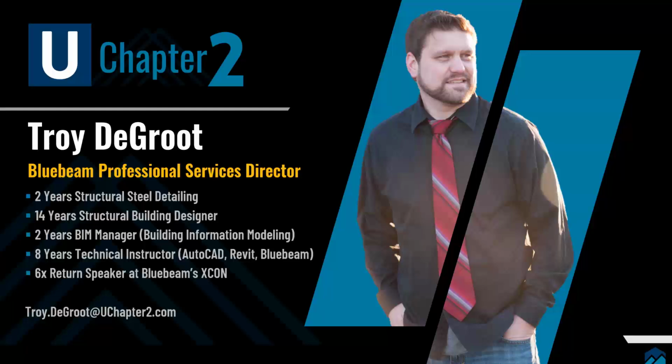This month's webinar is focused on one of my favorite, most powerful functions in Bluebeam called Quantity Link. This is a feature used for transferring tendering data from Bluebeam directly into Microsoft Excel. This is a live transfer of information, so as you continue to measure materials, the totals will automatically update in the spreadsheet. Because this webinar talks about just one feature, it's going to be a little shorter than others, but just like our training, we're going to get straight to the point and be done so you can get back to work practicing what you've learned.